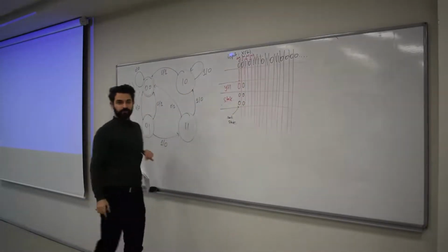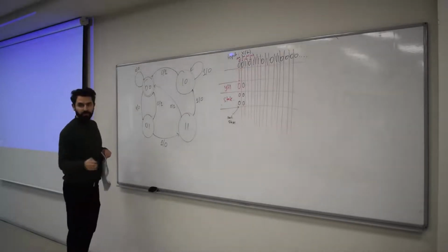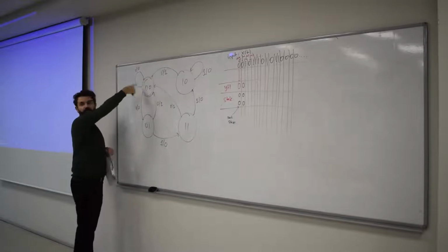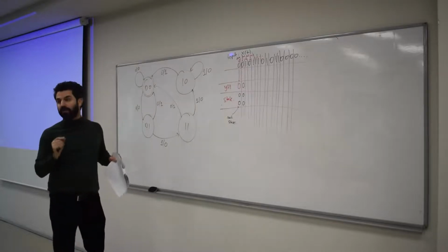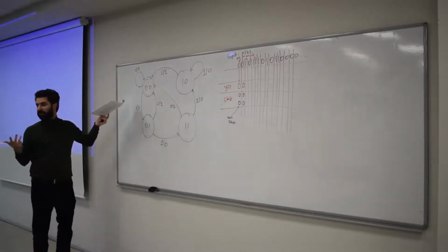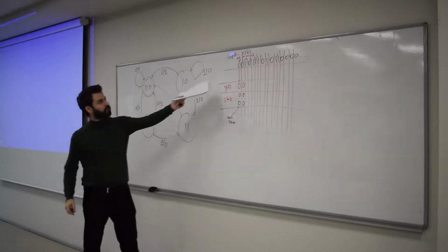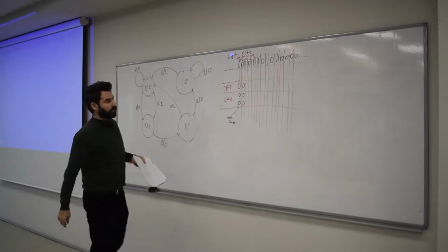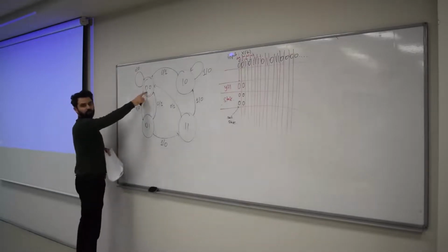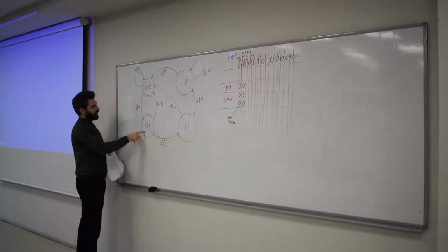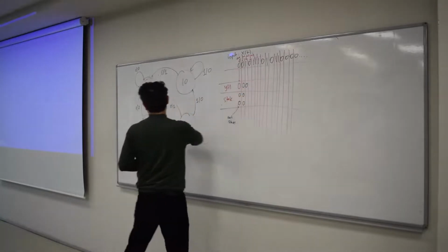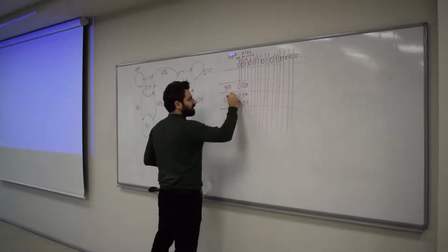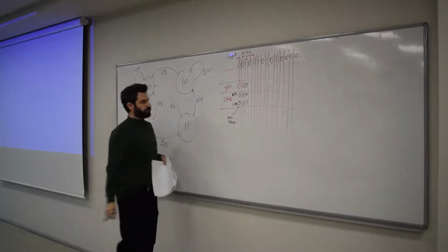And I've got 1. So as long as I see 0 at the input, okay, then that means I'm going to stay in the initial state 0, 0, okay, all the time. So input has to be 1 in order to leave this state. Okay, I think you can clearly see that. So let's suppose that the first input 1 comes in the third place, the t equals 2 case. That would actually push me to move from this state to this state. And that would generate another 0. Okay? So that is 0 again. But I am in this different state now. 0, 1. Let's just say this is MSB. And this is LSB, all right? Just a convention.